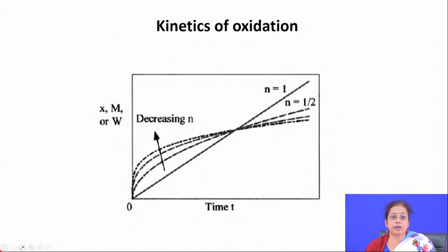If you think of the application of surface engineering in mitigation of high temperature oxidation, in many cases the alloy is responsible for the oxidation mechanism. So, you have to think of surface alloying with a proper alloying element, particularly silicon, chromium and aluminum. These are three alloying elements which offer very good oxidation resistance.